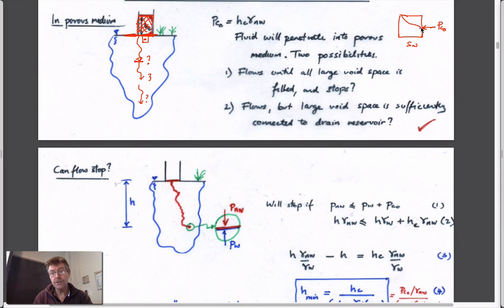So long as the pressure here is larger than this point, then it will go into it. PC0 is a number. And so if we know the unit weight of the fluid, then we can calculate what the height would be that we'd have to increase this head to be able to physically go into the system. That's really all we're saying. So we can calculate that.